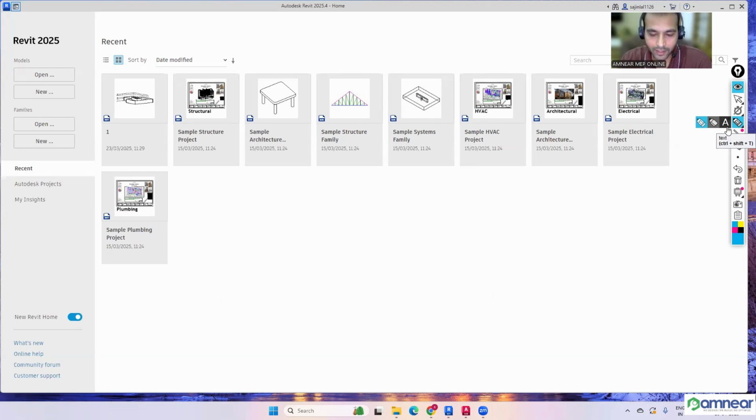As you know, when we are working in the MEP industry, we have four types of layouts, right? Five types actually, but four main drawings: tender drawings, IFC layout. So tender and IFC have to be prepared by the consultant, and the next two, shop drawing and as-built layout, have to be prepared by the contracting company only. But whatever changes the shop drawings have within the site, we will be marking with the help of a red pen. That is called the red line layout. So with the help of the red line layout only, we'll be making the as-built layout.